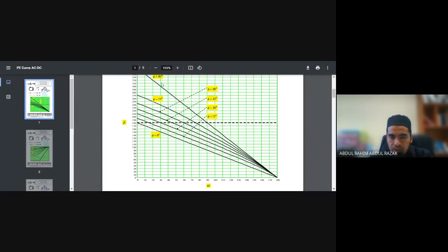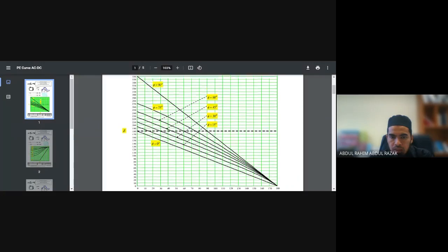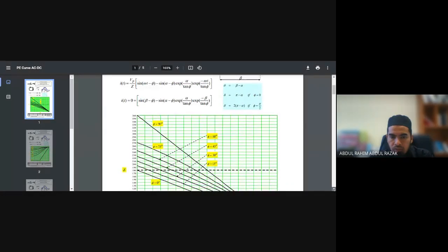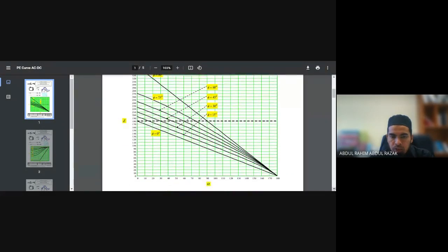Let's say the highest curve means that only the inductive element dominates inside the circuit. The higher the alpha you trigger, the longer the extension angle. So this is the curve. If you trigger at 90 degrees, for pure resistive load, it will diminish at 90.